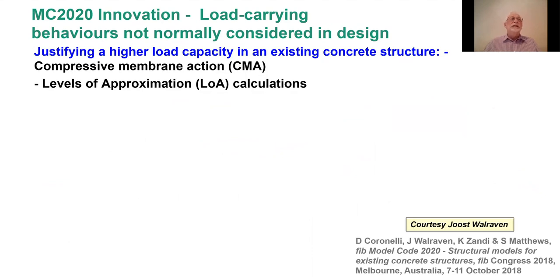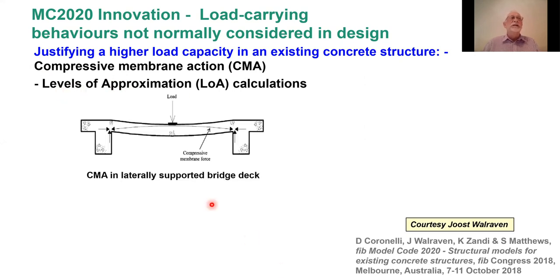Let's look at an application of this concept in terms of justifying a higher load capacity in an existing concrete structure using compressive membrane action and levels of approximation calculations. So here we have compressive membrane action developing in a deck slab by virtue of arching.